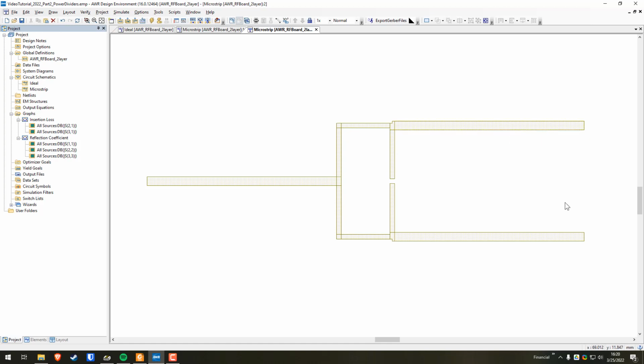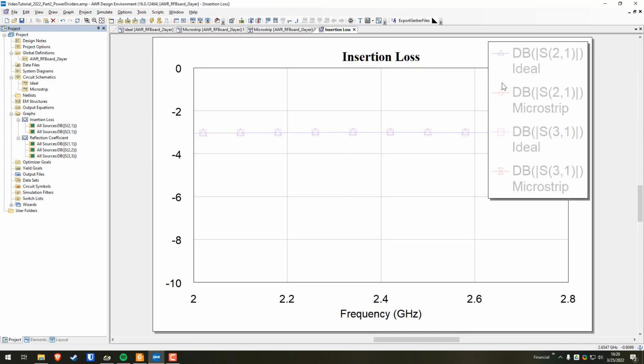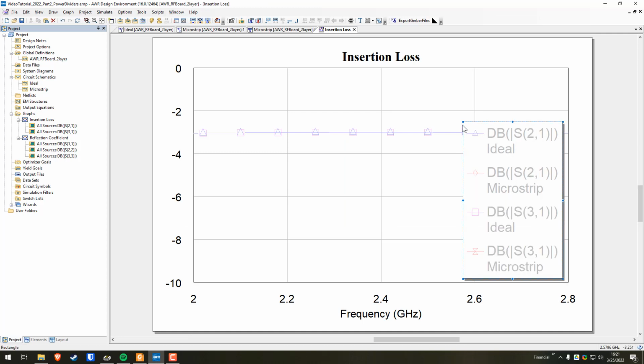because again, it can be a power combiner. If you feed 2 signals into the symmetrical legs, they'll combine at the junction and you'll feed out as a power combiner. Or if you feed the input here, the single line, it'll split off the junction and you'll have a Wilkinson power divider configuration. So let's go to the insertion loss first, because it's the first one on the stack.